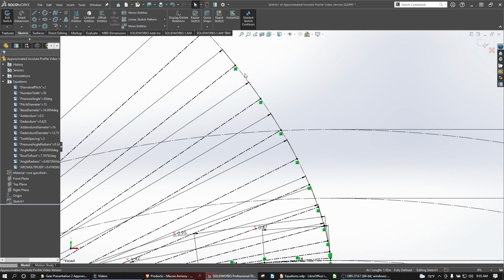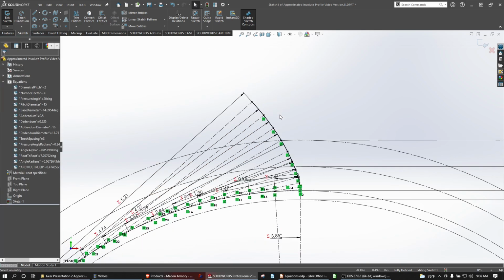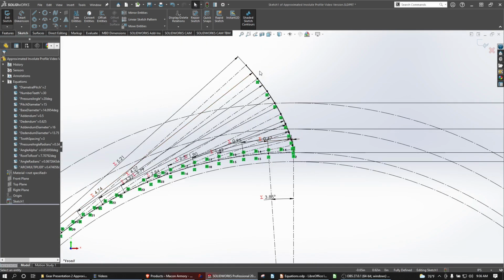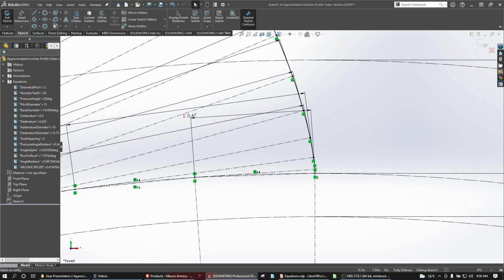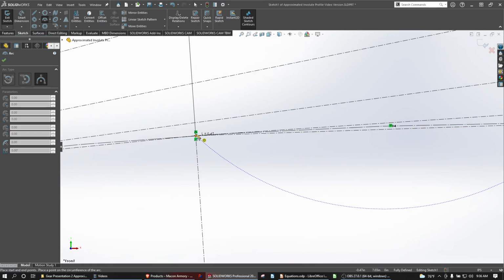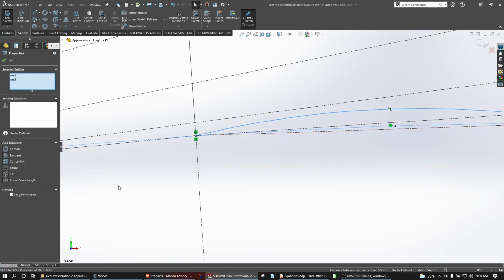What I would do is multi-body modeling. However, I do recommend you play around with the sketching method of the splines, as it can be quite helpful to understand how these models update and so on. But instead I'll make this spline a driven feature, and all right, I should say a sketch feature, right? Not a construction feature. I for sure want to make a solid arc from here to here. And we have our circle updated, and we say equal.